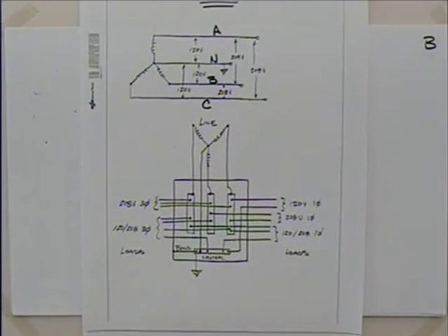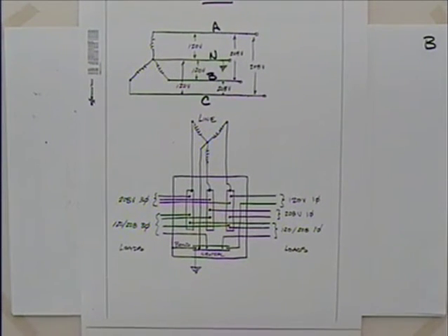If you look at a three-phase panel like you might have in an industrial setting, this is not something, as I mentioned last time, that you're going to have in your house. But if you go to an industrial setting, if you want, we can take a tour of the electrical panels down in lab, and I can show you the difference. But this is showing you the layout of the panel, how you can get single-phase circuits and three-phase circuits out of the same panel. When you start pulling single-phase circuits out of them, you can begin to unbalance it. But if you pull 3 single-phase circuits out of it, you stand a chance of keeping it fairly balanced. So that's kind of a practical drawing there.